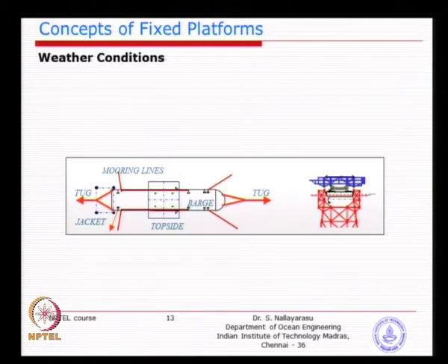So, you will have 8 legs on the deck, whereas 4 legs on the jacket, because 4 legs support the deck during transportation, on the inside, and 4 legs will be hanging in line with the outer legs. So, when you go inside there, just set down.